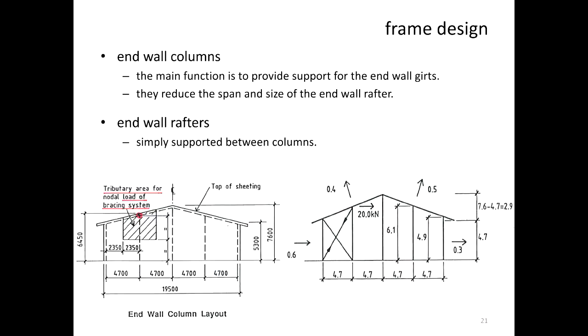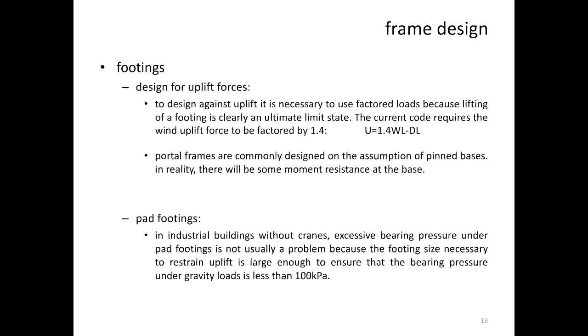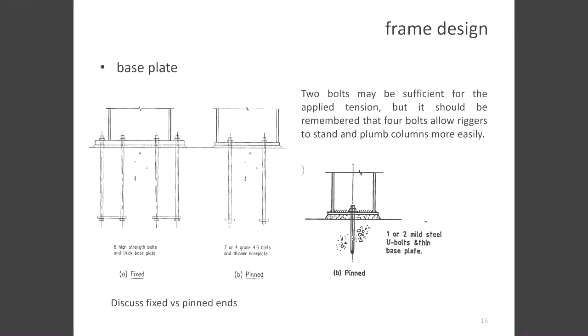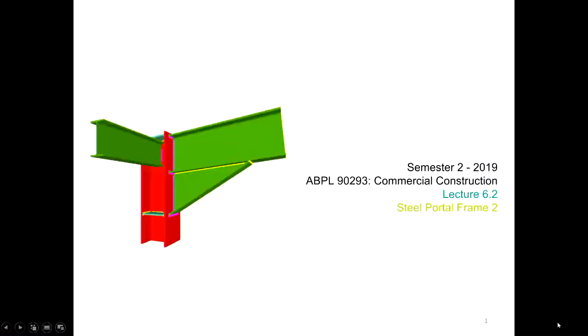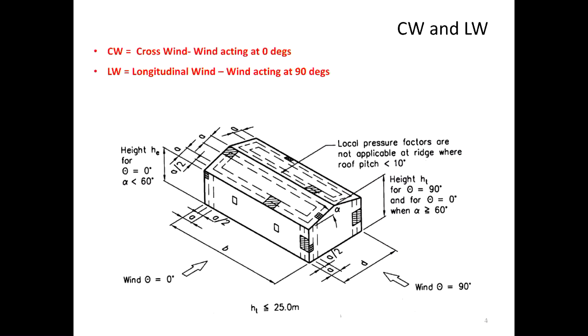Now there's a reason, because if you go back to the very first slide, what's going on? When you have that, you've got a braced end at the top, which I'll show you shortly. You've got wind load in the crosswind direction, which will be resisted by these walls. And wind load in this direction, most of that will be transferred to the longitudinal walls.